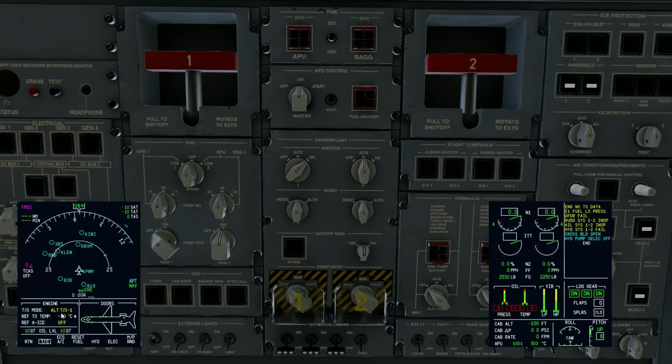That's the temperature we set. We don't do anything else here. We just set the outside air temperature. And the goal is to try to be within 3 degrees. So obviously, by the time we taxi out, it might warm up a little bit. And as long as you're within 3 degrees, you're in the ballpark. But if it's more than that, you might want to reset your data. And that's all we set there. We don't do anything else. No artificial flex.